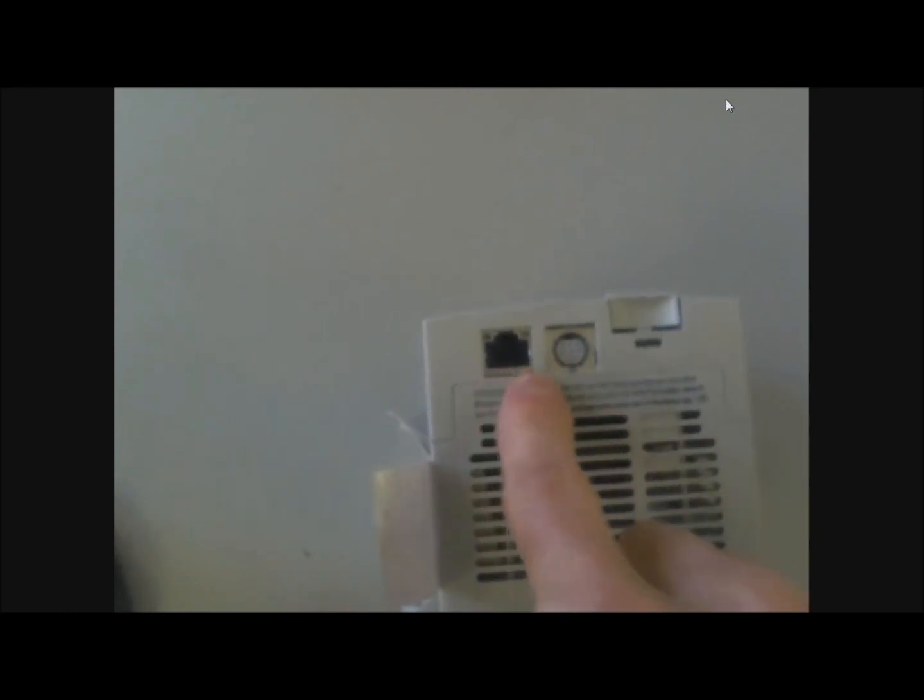This guy runs off 120 volts. We'll talk about that a little bit. And these are the ways we can connect our computer. We can connect it through an Ethernet port, or we can connect it to what Allen Bradley calls a data highway port. All ours down there right now are connected by data highway. So you'll see an adapter, we call them dongles, that takes a USB port and converts it over to the data highway port.